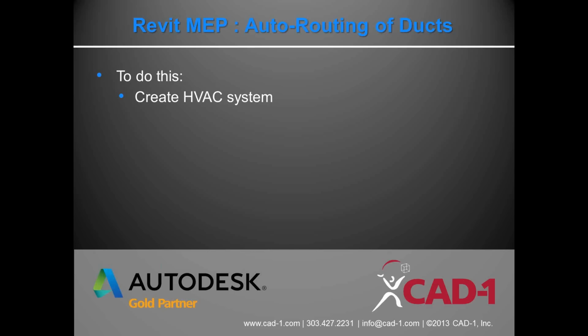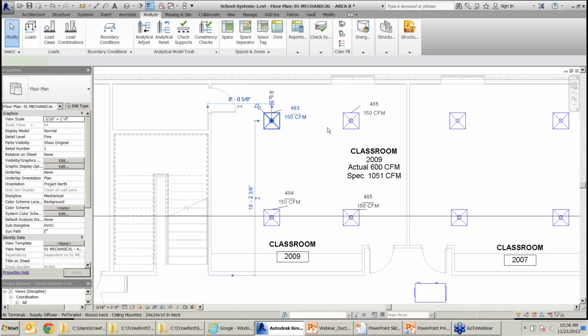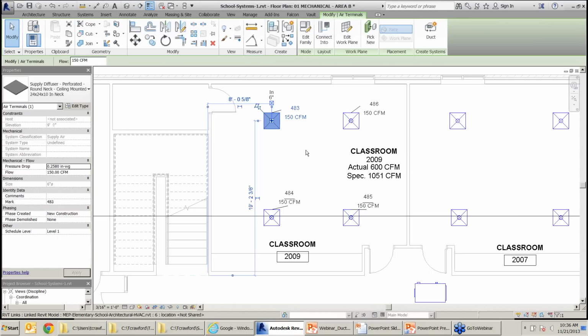Okay, so maybe we're getting a little farther through the process. I've got my air terminals in there, made at least one DD submission. Now I'm going to start creating a system, so I'm putting my equipment in there. So to do an HVAC system, I need to have air terminals. Okay, I already have those. Now I need to add the mechanical equipment. So let's go back to Revit. I have my air terminals in here. They're not assigned to any system yet. Good, I'm just verifying that.